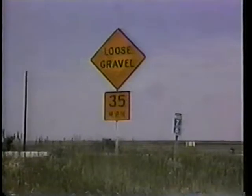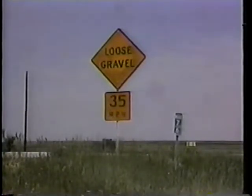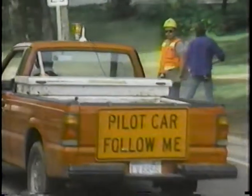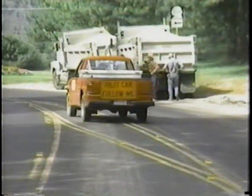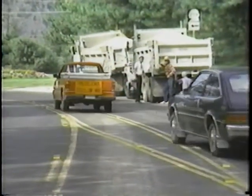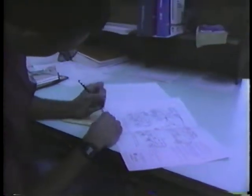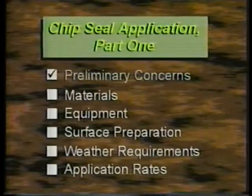On long jobs, advisory speed signs should also be placed every 2 kilometers or so. To further protect motorists and the new chip seal, pilot cars may be needed on projects constructed under traffic. So carefully review the traffic control plan, make sure it's approved, and see that it's followed throughout construction. The next step is to check the materials.